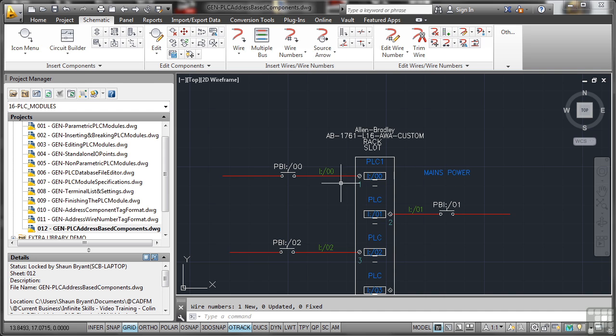You can do it manually, or you can also, like we've seen previously, set your project and your drawing to find the information. So this input-output auto search can be found in your project settings, or in your drawing settings, or you can do it manually when you edit the components or tag the wires. Very cool, very quick, very efficient. Use it, it will make you a lot more productive in AutoCAD Electrical.